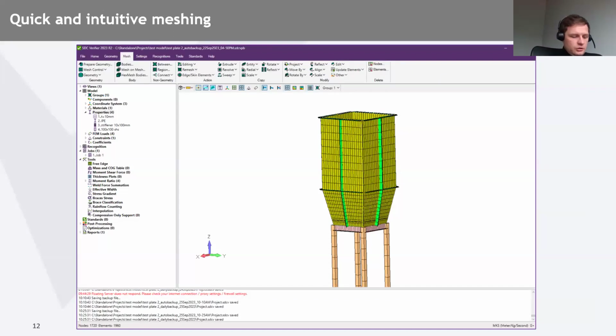After the initial stage of geometry preparation and modeling is done, it is necessary to proceed with building the finite element analysis mesh, defining the parameters, materials, and properties, converting our geometry file into a finite element analysis model.